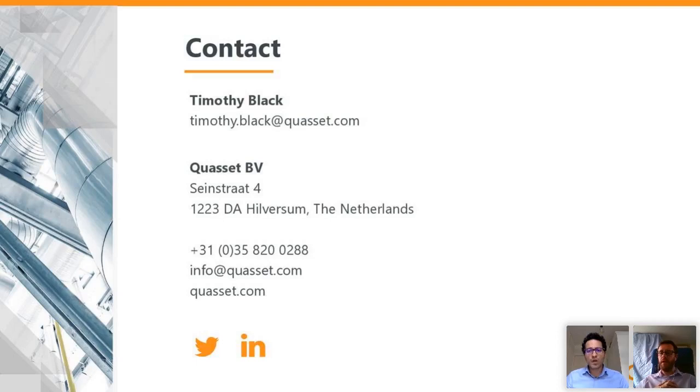So with the flanges and the piping, it's all based off the ANSI and ASME codes, and they're parameter driven from the NPS, the nominal pipe size. So you put in the size, and if you connect a flange to the end of the pipe, it's then built based on the codes and the tables that we have, and it will be to spec.